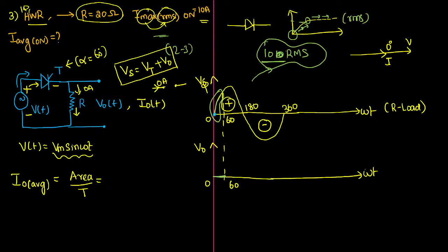Okay, sir. So after 60 degrees, what will happen? Till 60 degrees, the sinusoidal voltage keeps on increasing like that, so from 0 to a certain point this voltage will be blocked by the thyristor. From this moment onwards, once the thyristor is turned on, the thyristor will be short circuited. Off state means open circuited, on state means short circuited. Once the thyristor is short circuited, the remaining portion of the supply voltage immediately starts appearing.